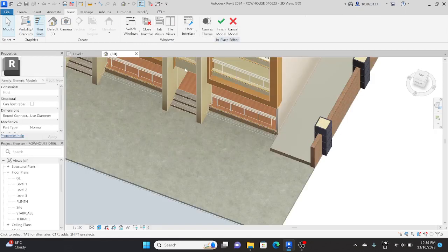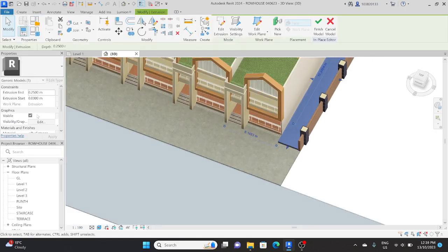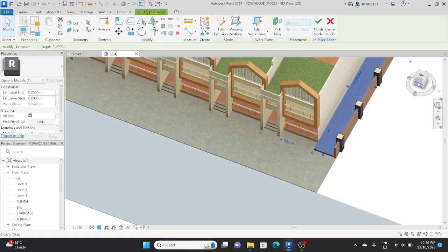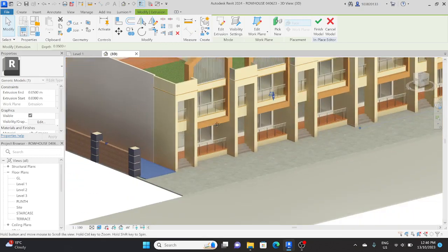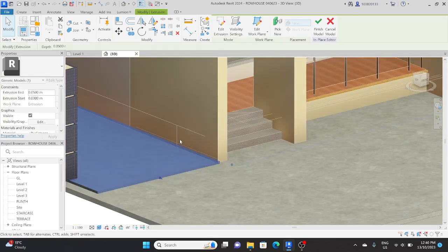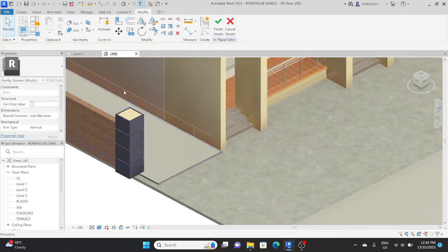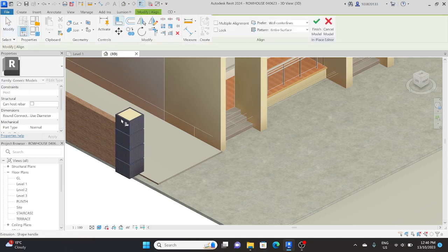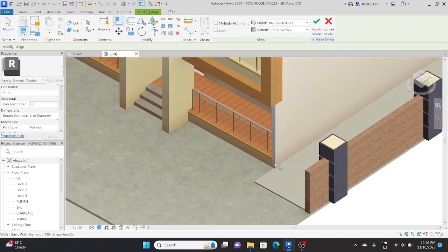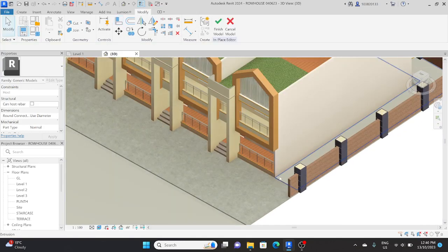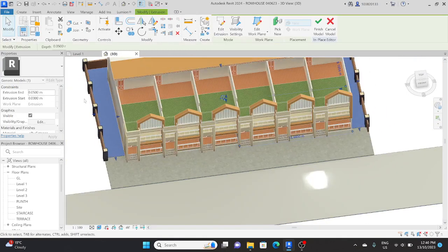Okay, in the properties bar we can further just give it a small thickness to it, so say about 0.05, and as you can see there is some sort of thickness to it, and we can just align this over here and aligning it with over here, and we can assign this material as grass.